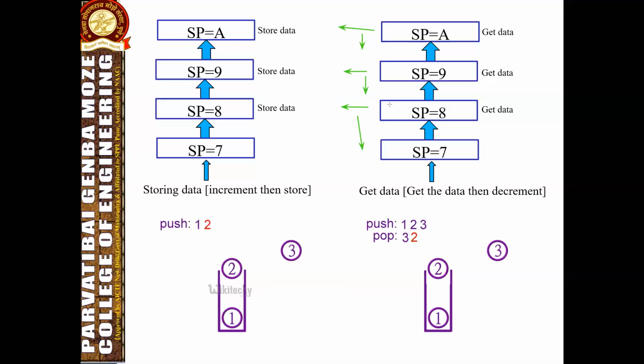When the 8051 is restarted or powered off and on again, the stack pointer holds the address 07H.